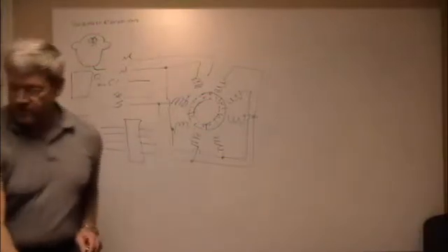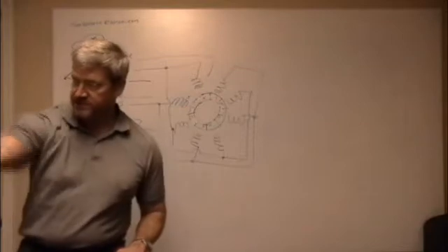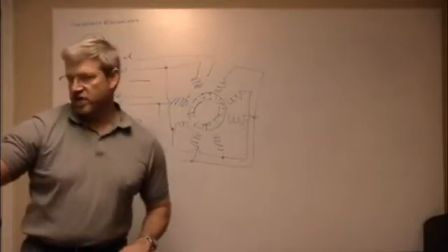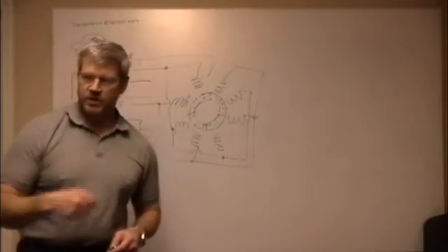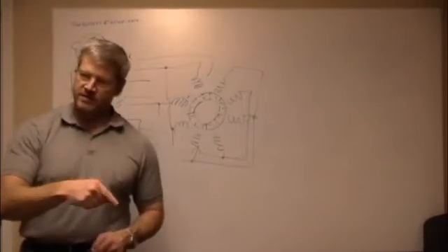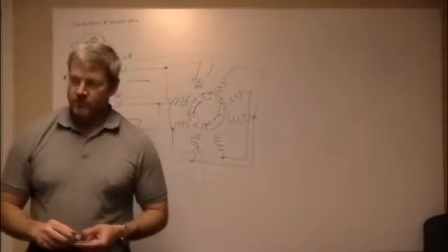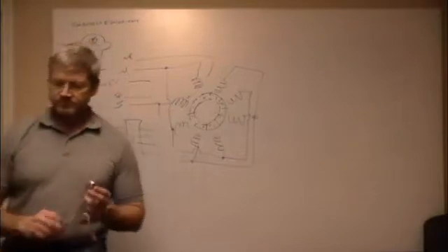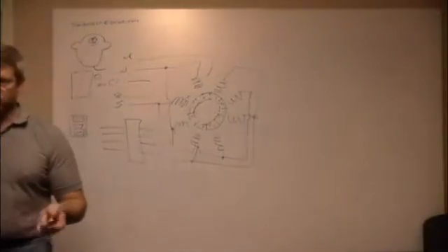So you saw how I was doing this. It would go tick, tick, tick, tick, and then it would zip back. That zip back, I just changed the value from 180 to back to 100, back to 0, and it went right back to 0. So it knows where it is in space, whereas this doesn't. Okay. But there are reasons why you want to use one over the other.